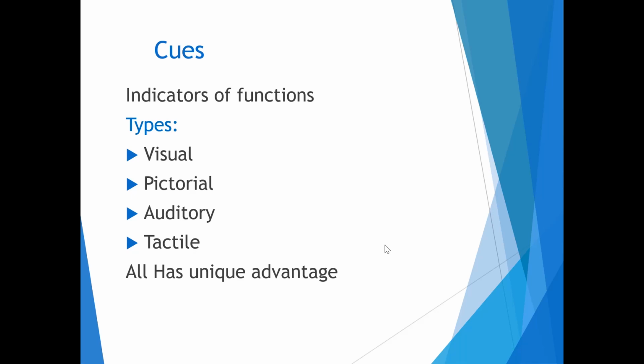Tactile cues can use size, shape, force and texture to differentiate functions. They are good for controls that an operator manipulates without looking away from another task. Tactile cues, this last one, have size and shape limitations. They cannot be very small or subtly shaped.